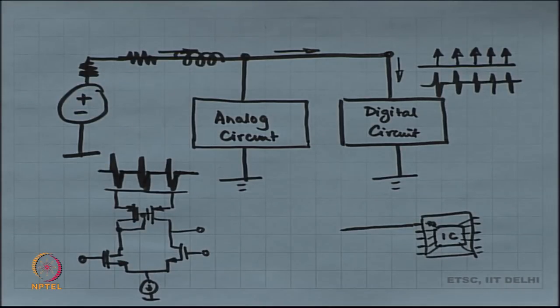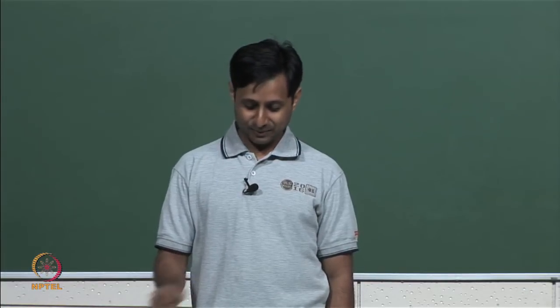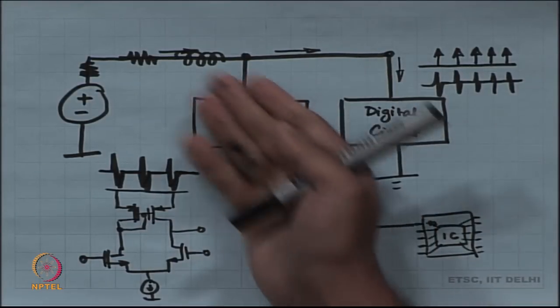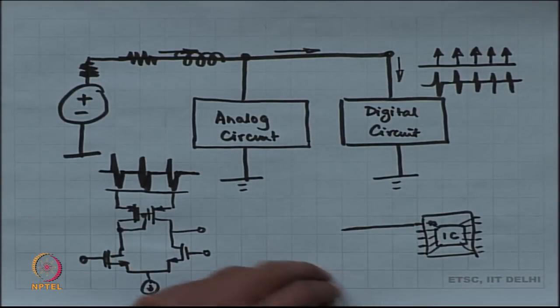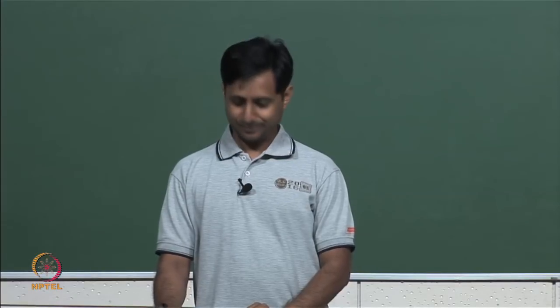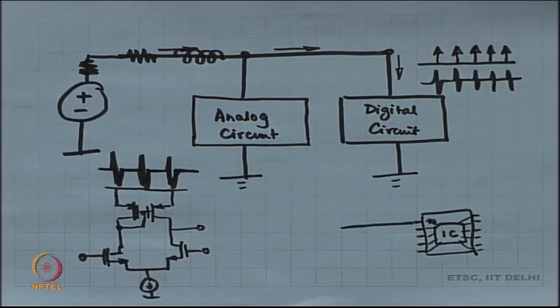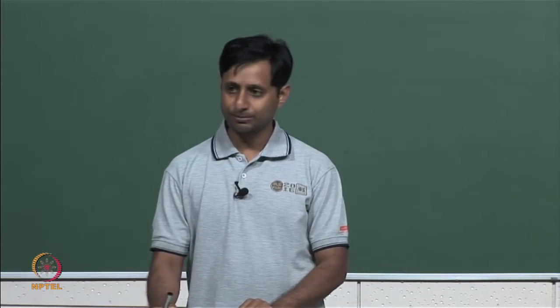So, this is a problem, and whenever there is a potential problem, Murphy has said that that problem is going to crop up in your life. So, I am identifying this as a potential problem, and guess what, this inductance in the power supply wire is everywhere. So, we have a problem. The problem is that the power supply to the analog circuit is not good, it is not the VDD that you want, it is not a constant voltage.